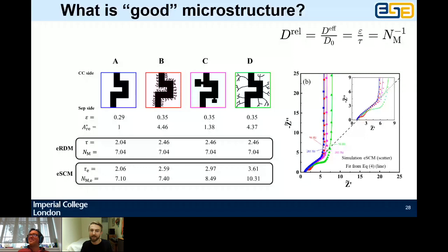Have you performed modeling validation for various electrode thicknesses and calendering forces applied? If you have, have you checked if the tortuosity factor is constant during cell cycling at various applied currents? Those are two fantastic questions. The answer is no, but Tu and Charles and also Alejandro and his team are working on these things, trying to characterize these microstructures at different calendering, as you've seen over the course of this week. I think we're in the moment now in battery history where this is going to happen, and we're going to get these relationships established and finally allow us to optimize batteries.